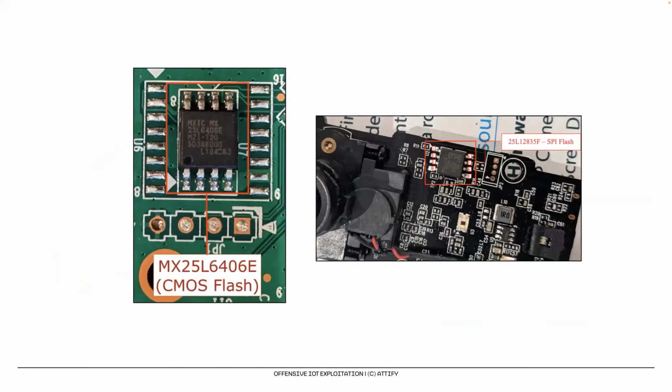The next protocol that we can look at is SPI, and this is the protocol that you'd most often find in flash chips, which are the chips that store data. It's also found in other chips such as chips for networking, encryption, crypto, sensors, and so on. This is how a typical SPI flash chip would look like with 8 legs. It can have other variations as well, but this is one of the most common layouts. And in both the cases, it's an 8-pin SPI flash.